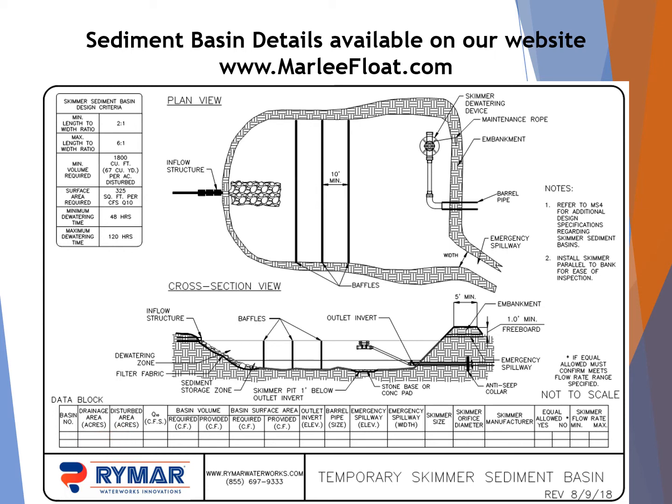this as needed. It includes drainage area, disturbed area, Q, whether that's a Q10 or Q2 based on your basin design. The basin volume, again, your provided can be greater than your required, but you want to list the required since that's what you're going to base your skimmer sizing on. The basin surface area, make sure your provided is greater than your required.